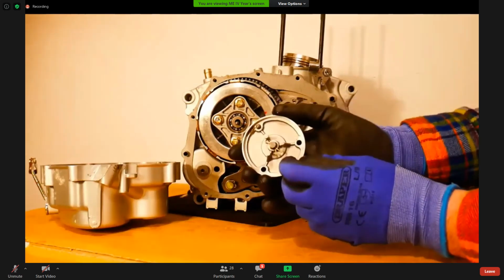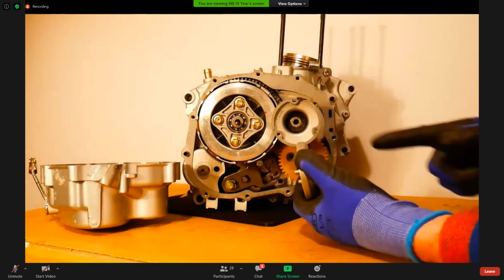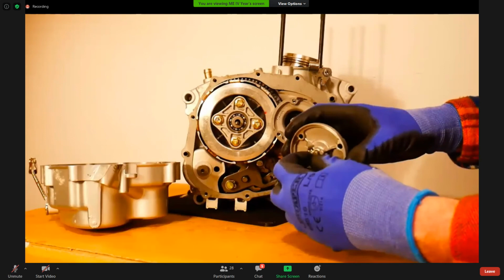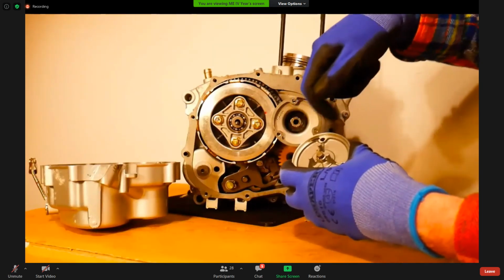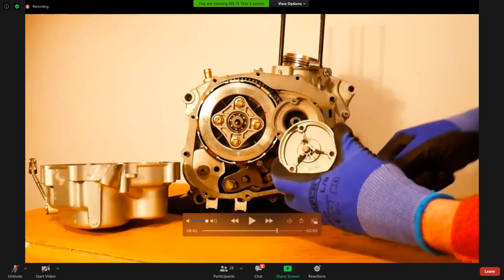And the reason for that is that when the oil comes in through the valve, it hits this little plate, I suppose, and hitting that forces it to move in this direction. So it moves to the outwards direction, away from the center. So as you can see here, you have some obstruction, and in the sideway there are holes. So when the oil is coming from the oil pump, it is moving in towards the circumferential direction, and it will be forced to go towards what you can say is the inner rim of this filter.